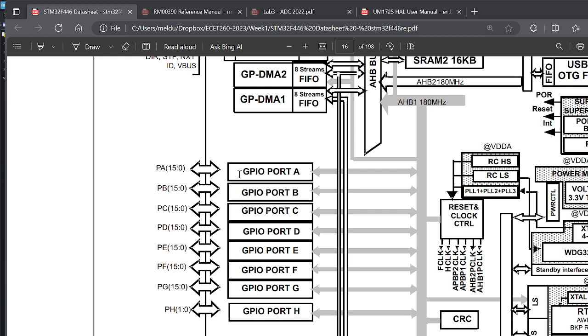This is a real-time clock module. And so I can actually set it up and with a battery backup, have this thing running, keeping track of time. You can set things up like wake up once a year, wake up every day at 8 a.m., do all of that kind of thing. And on board, you have a 32.768 kilohertz crystal on the Nucleo board to take advantage of that. By default, they don't have the battery and things there. There's a VBAT pin. You can hook an external coin cell to it and set all of that up.